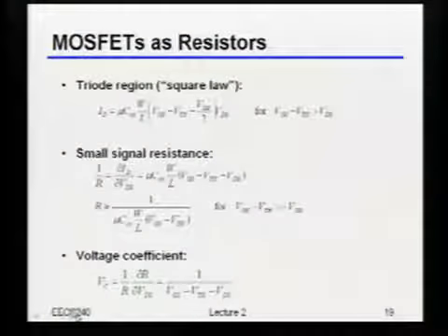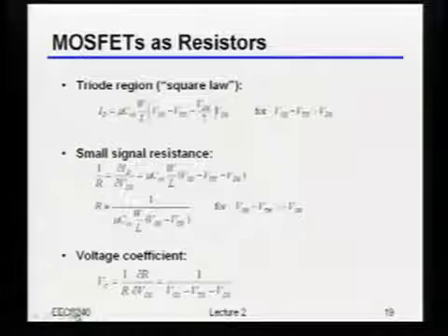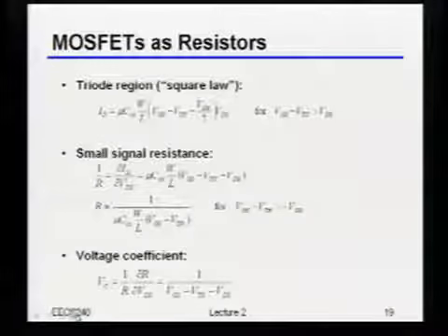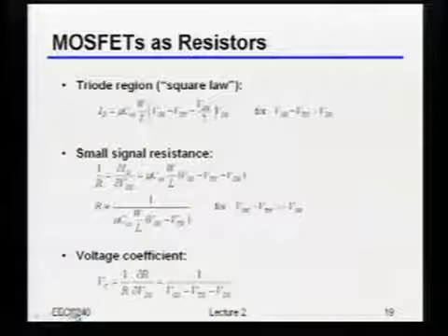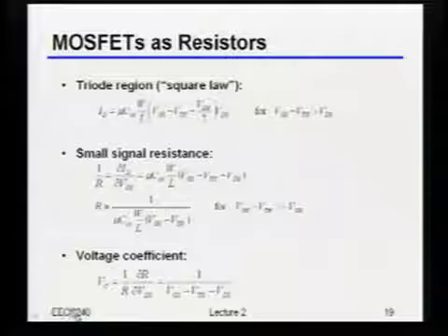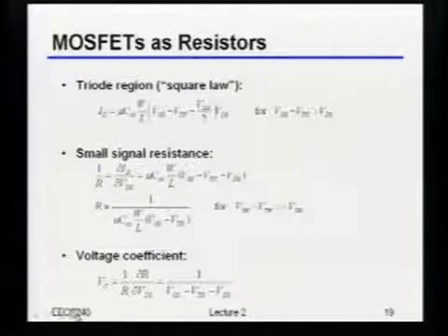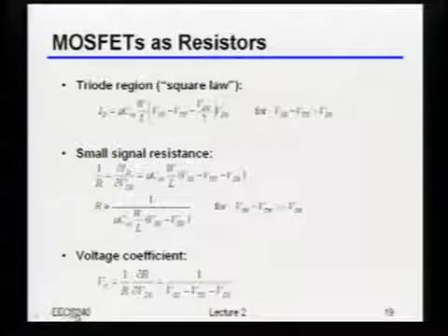Okay, so just one last brief thing on resistors. We said we can get maybe somewhere like 100 to maybe a kilo ohm per square. If you really want really, really big resistors, that obviously gets big quickly. Let's say you wanted a gigaohm or something like that. That gets painful. So in some applications, you will actually end up just using a MOSFET as a resistor.